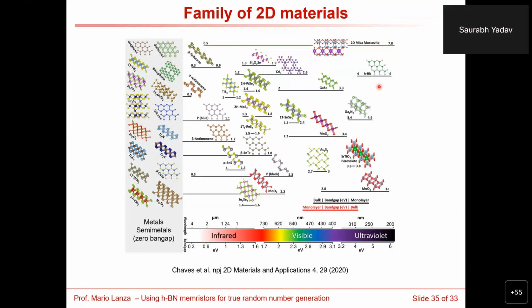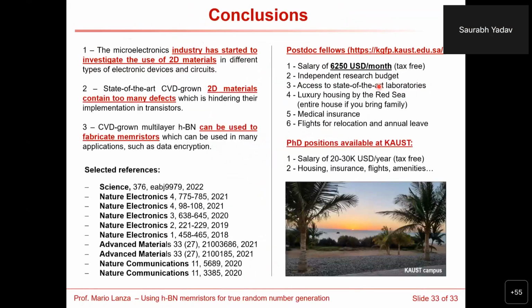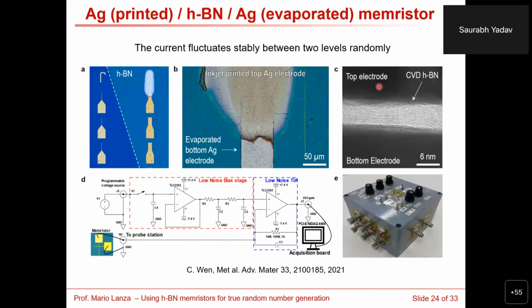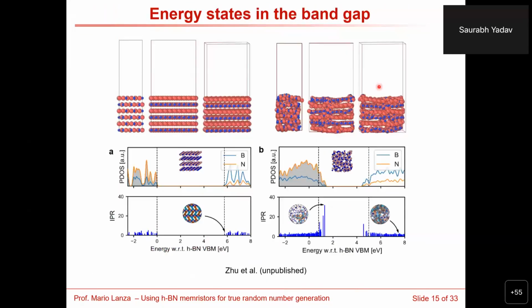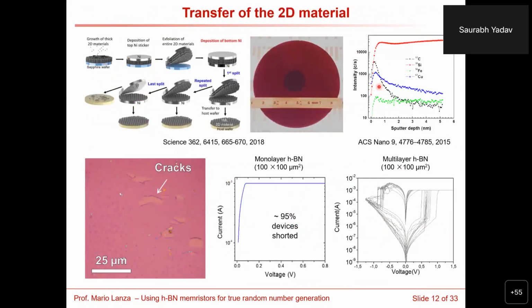My next question is related to the removal of boron nitride. As you have mentioned, first you deposit the boron nitride by chemical method on the whole substrate. During the contact formation, you remove or etch out the particular boron nitride from the substrate for a direct contact of a metal on that semiconducting channel. So which technique can we use to completely remove the 2D material? Any chemical technique you have used for the formation of metal contact on 2D semiconducting material?